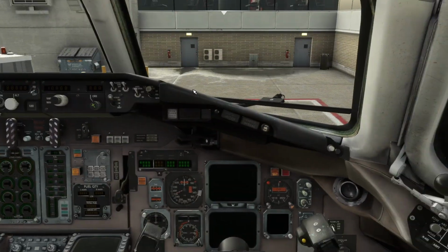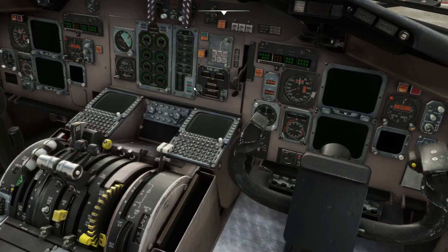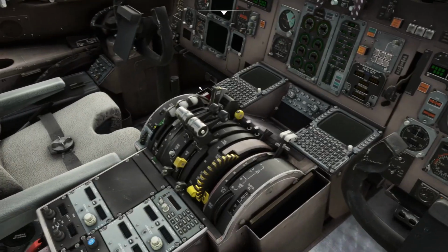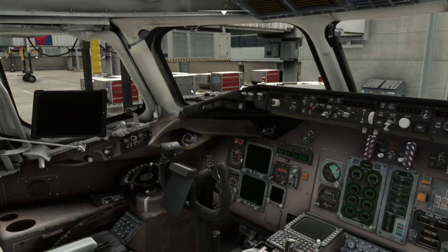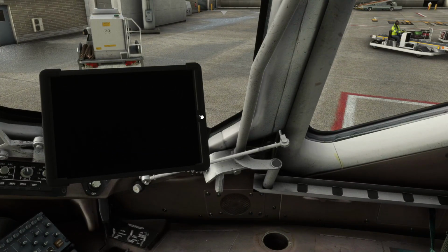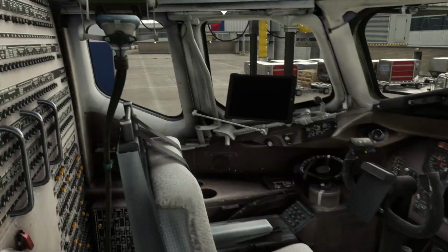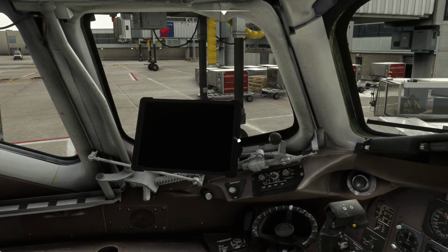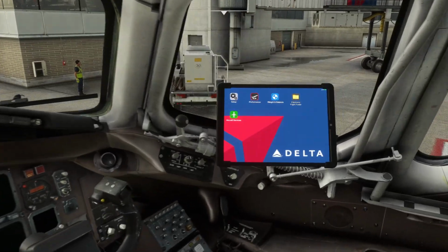So the cockpit. It's very daunting. We're going to be flying as first officer today. And yeah, it is a very complicated looking thing. First thing you need to do really is to turn on the EFB, which is done by holding down the home button. And that'll take a couple seconds to boot up. We can do the same on the captain's side as well, for no reason.